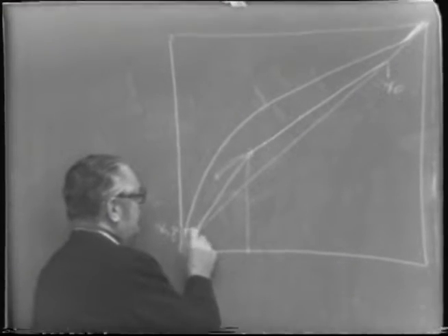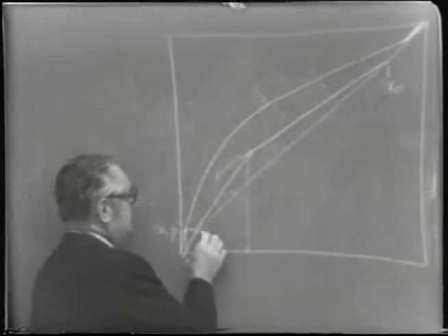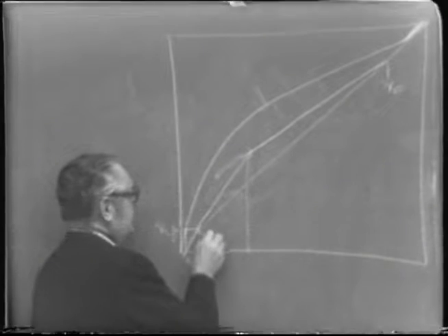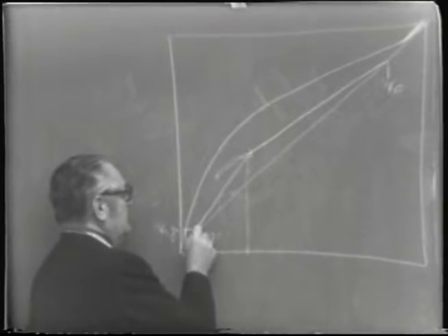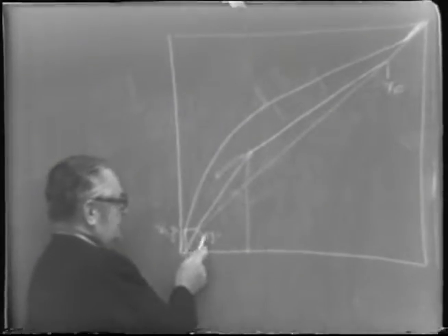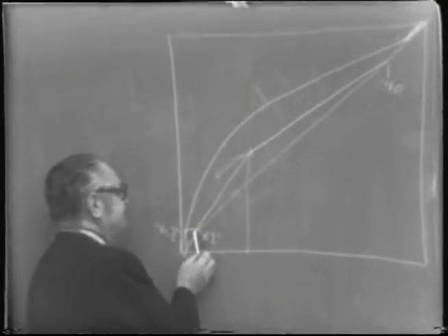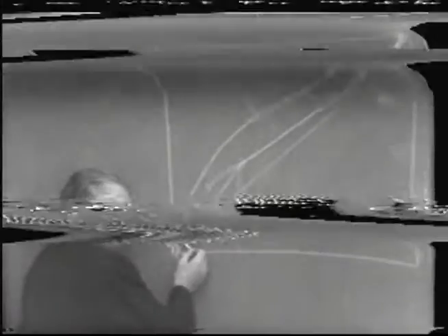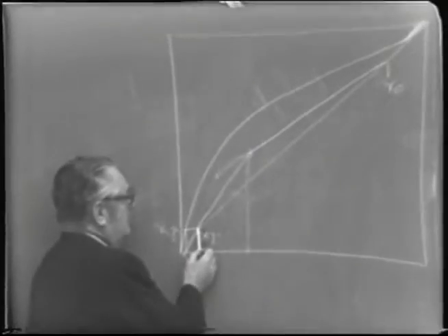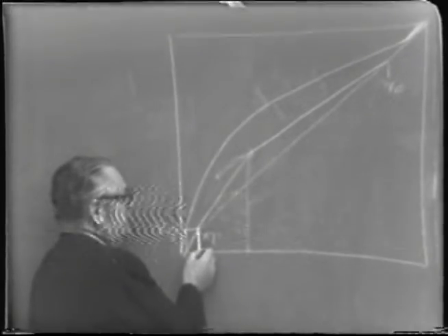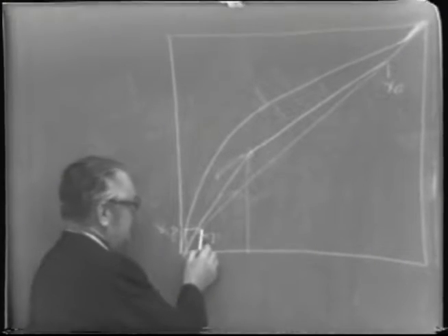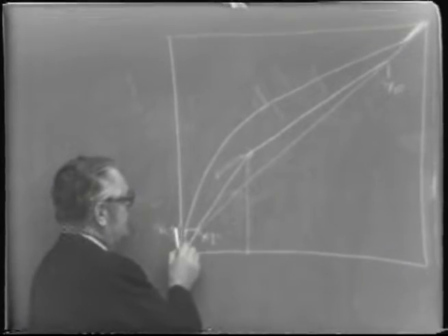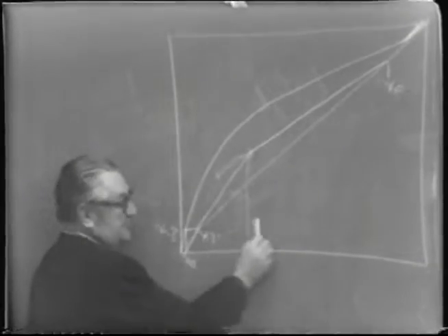And then if you take the step over here, this point here, of course, is x1, y sub 0. In other words, this on the operating line is the composition of the liquid on the first tray above the pot, and the vapor that's arising from the still pot. And of course, numerically, this y sub 0 is the same as that if you project it horizontally.